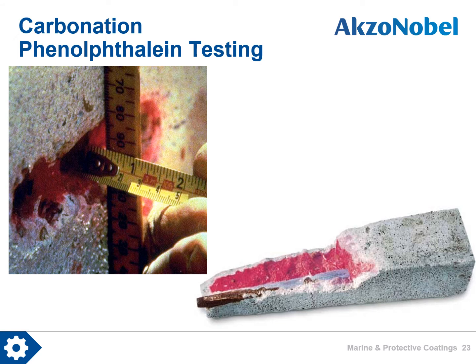Here we see testing for carbonation using phenolphthalein sprayed onto the concrete substrate. Where it is purple, the concrete is not carbonated. Where it is clear, it is carbonated.